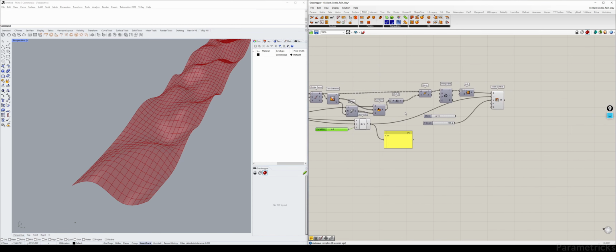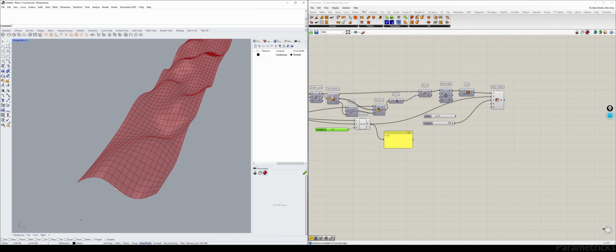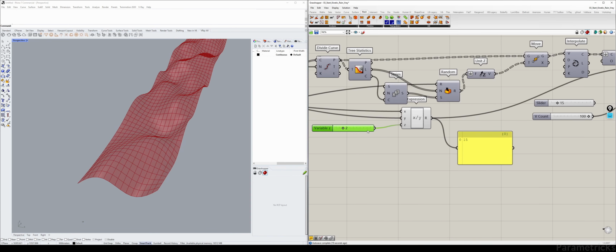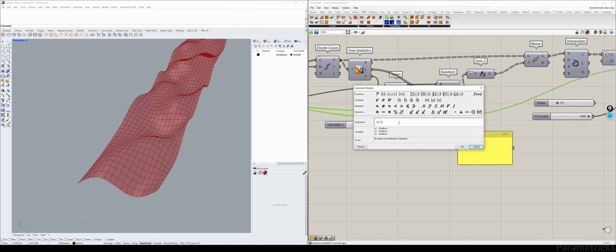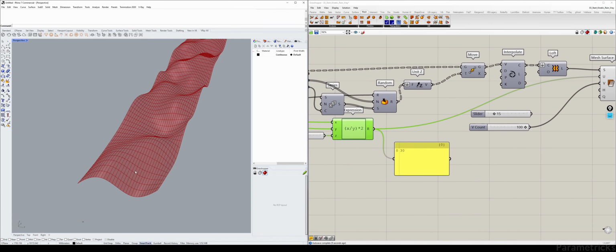Right now it's 15, and when this gets wider, it will just take the average or similar in-between distance, but we want a little bit finer mesh. That's why we introduce this 2. Whatever number that is, times 2, which will give us a little bit finer.